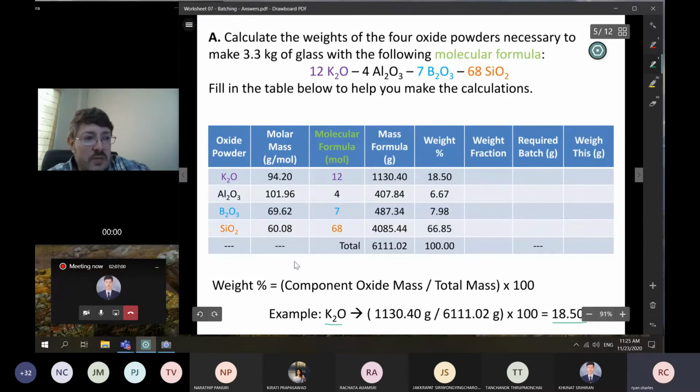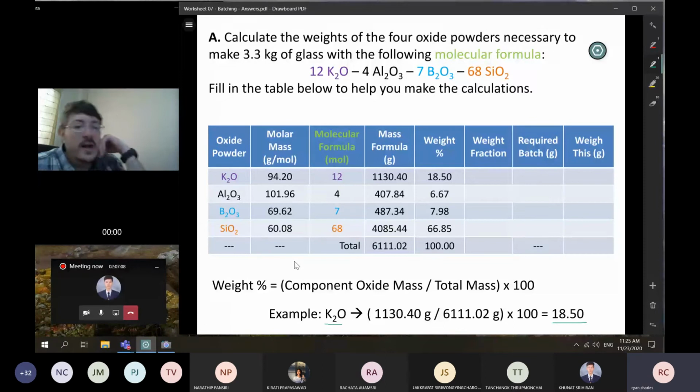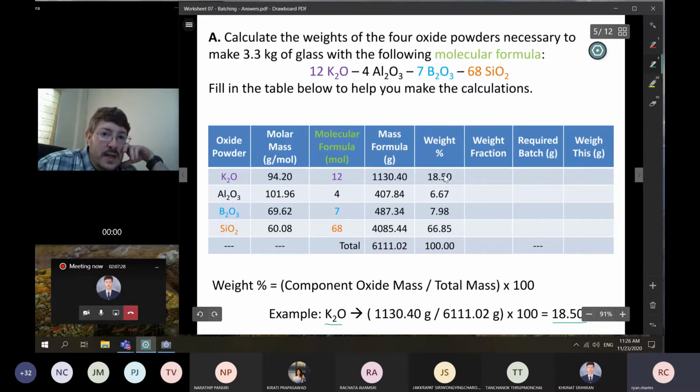If one of these elements provided color, you get the wrong color, right? Instead of light blue, maybe it's dark blue. You have to be aware, when you're going to batch together materials to make a recipe, that you don't make rounding errors and add too much of something than what you thought you were going to or should, because the properties can be affected. If you're off by 1 decimal place, you'd also get addition errors where it wouldn't add up to 100. It's not hard to get it to add up to 100. You just have to pay attention to the numbers you're calculating.